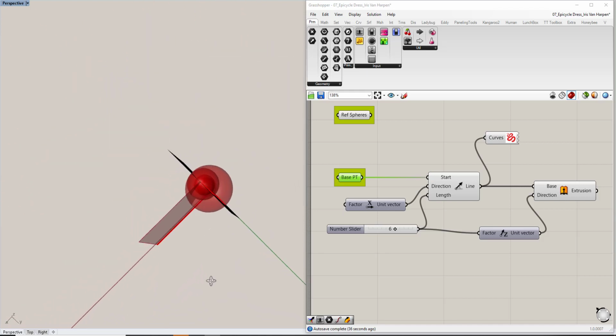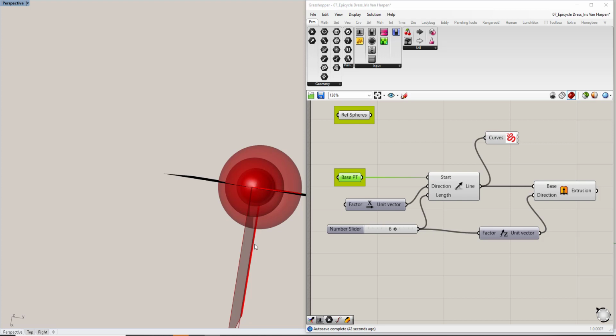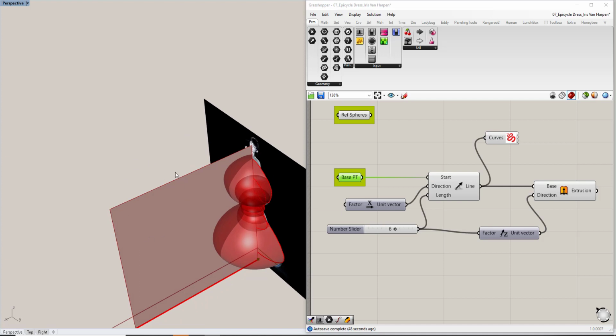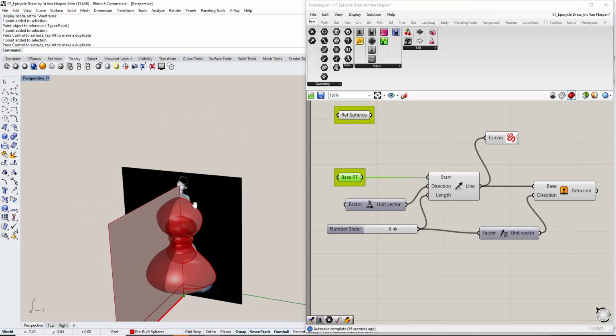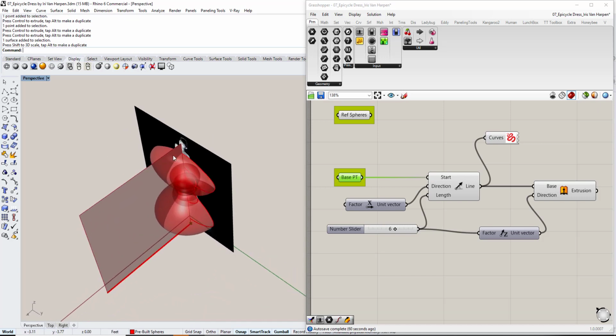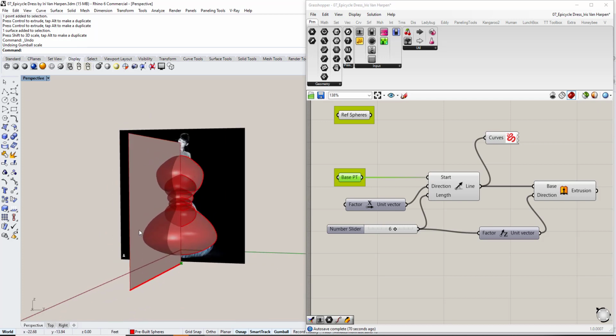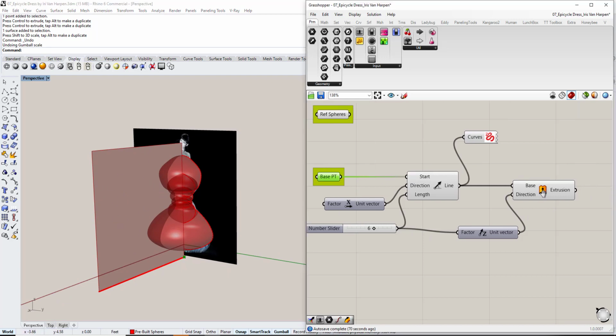That's really all I need, because what I can do now is intersect this with the shape. Now, you could do this one of two ways. Either you do the intersection first, and then you take the curves and do the array around, or you can array the rectangle here. I actually prefer arraying this plane first, because say I did want to make a change to one of these shapes, and I wanted them to be a little bit wider just in one direction, then if I do the intersect and then rotate the curves around, I'm not going to be as accurate, right? It's going to be the wrong information there. So in order to stay consistent, I'm going to go ahead and polar array this rectangle here.